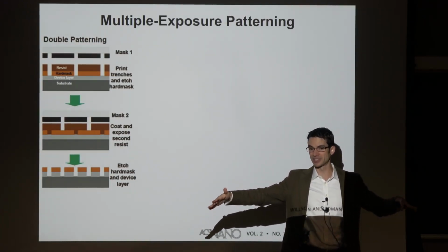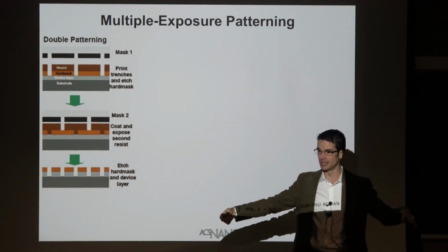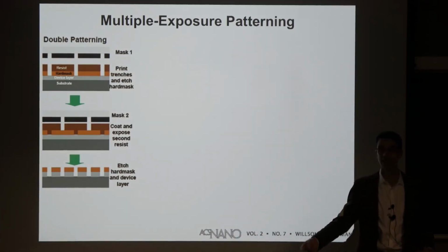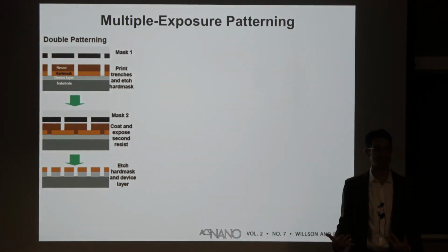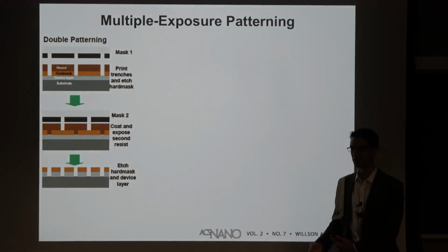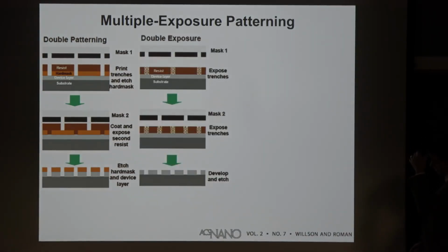Because those are sub-threshold exposures, which are actually producing some of the chemical reactions that cause the film to become soluble later. So what that's called is a sub-threshold exposure, and what we're asking the film to do is forget the sub-threshold exposure, which it can't do. There are, however, chemical engineers and polymer engineers that are working on photoresist films that can actually forget sub-threshold exposures.